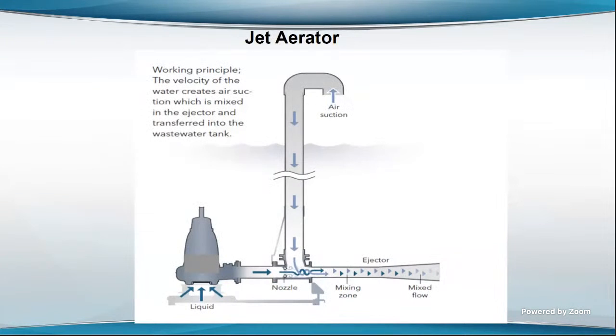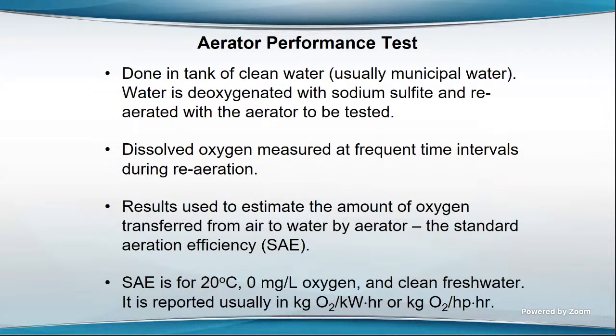And then these new jet aerators, they're kind of a variation of that Aero 2 aerator I showed you. They just have a Venturi device, and air is sucked down in here and mixed through this injector. And they eject the water horizontal to the pond bottom. That Aero 2 had to eject the water somewhat at an angle. These put it down at the bottom. So there's more use of that jet aerator now than used to be, but I think most of those devices are fairly expensive compared to the others.